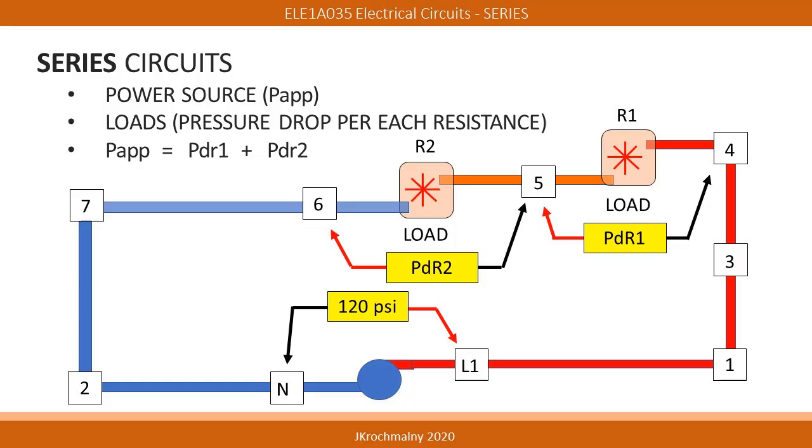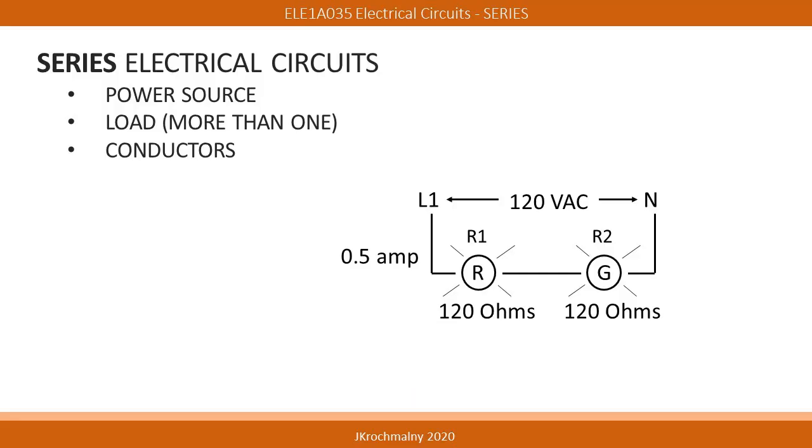Notice that the pressure dropped across each load, when added together, will equal the applied pressure developed by the pump. Energy cannot be created nor destroyed, but can be converted from one form to another. So, with this understanding, if we can apply this principle to fluid power circuits, we can also apply these same principles to electrical circuits.